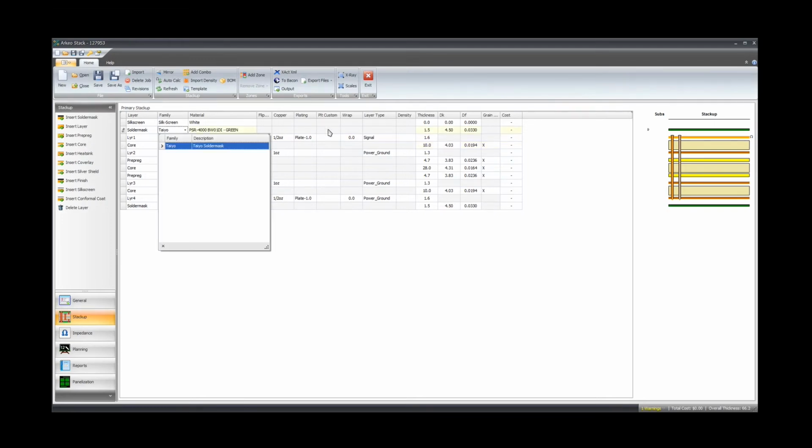It knows our solder mask dielectric constants. We'll see soon that that does play a role, whether you have solder mask on top of your impedance line or not. It has the dielectric constant for the solder mask that we choose to use in the model. The power ground spacing from the impedance design is known in the model. The pattern of the power ground, if it's a solid plane or if it's crosshatched, does play a role as well, and that's in the model we built here.